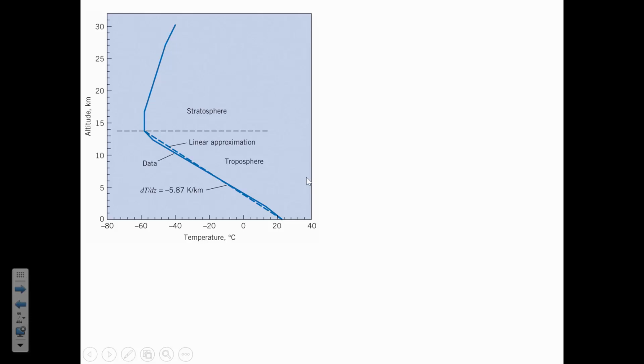Now, our atmosphere right here at ground level is about 80% nitrogen, 19% oxygen, 1% everything else like carbon dioxide, noble gases, helium, hydrogen, and so on. So as we go up, it's a fluid in the atmosphere. And we could look up a unit weight for air, just like water has a unit weight. And you could apply the hydrostatic equation through a gas in the same way that you could apply it through a liquid.